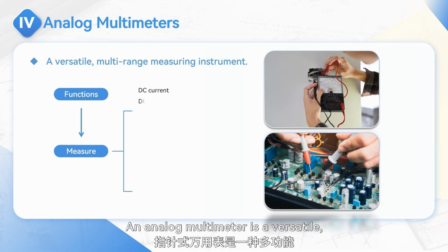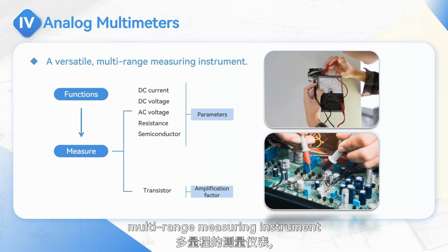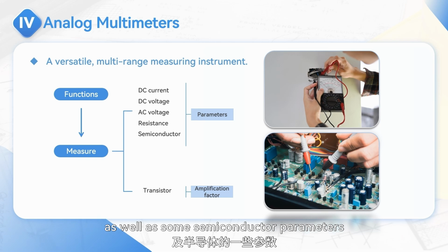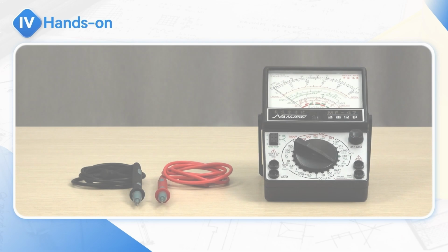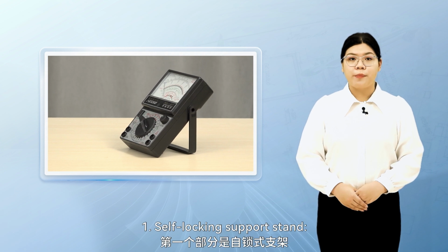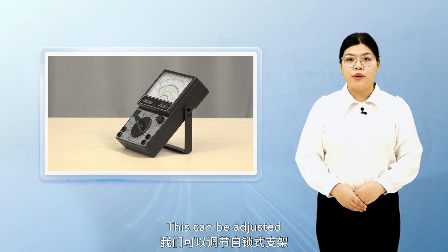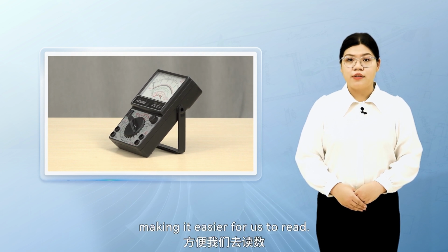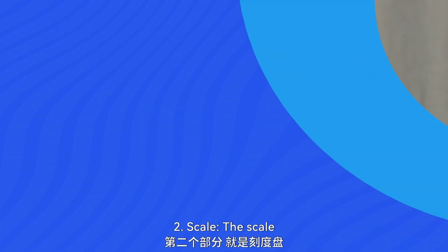An analog multimeter is a versatile, multi-range measuring instrument capable of measuring DC current, DC voltage, AC voltage, resistance, as well as some semiconductor parameters and transistor amplification factors. We divide it into 10 parts from top to bottom. 1. Self-locking support stand. This can be adjusted to align the scale with our line of sight, making it easier for us to read.